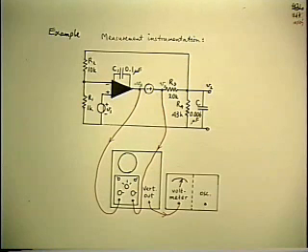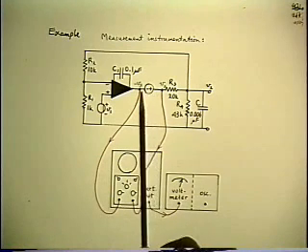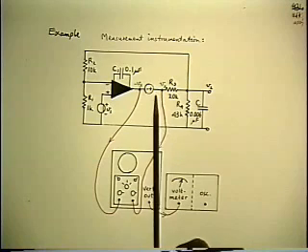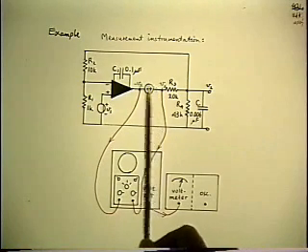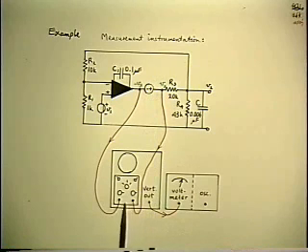The interesting thing is that you can measure the phase angle as well, even though the voltmeter measures only magnitude. And the key to that is, remember, these two voltages that we're measuring are 2 out of the 3 that form a phasor triangle, because we could define the sum of the 2 as Vz. We've already done that. But it's the phasor sum of these two.